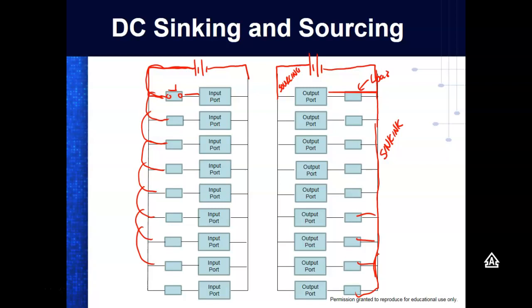So you need to understand how your plant runs, how they run predominantly. You can get a meter and measure this common going to your other devices from the other side. If it measures plus, that means the device is what? Sourcing, right? But that's very, very important.